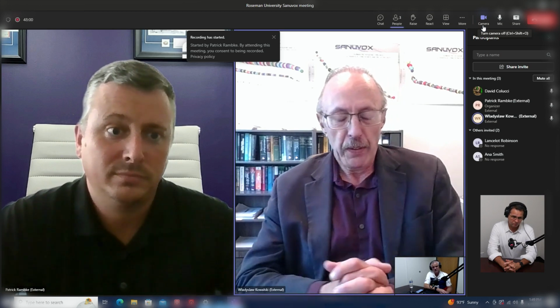They have proposed 30 watts total UV electrical power draw for a 200 square foot area. We find that is more than adequate, and all the test data throughout history suggests that works very well as long as your room mixing is good. Therefore, as a minimum, we would accept CDC's estimate on wattage per square footage for upper room units and also for far UV, which is very similar in operation and in power requirements.